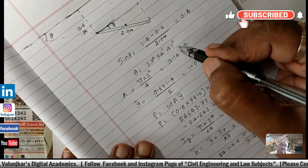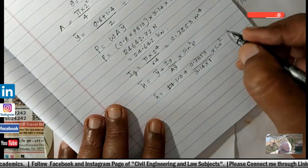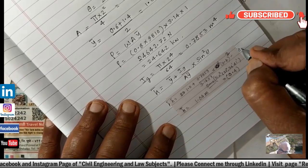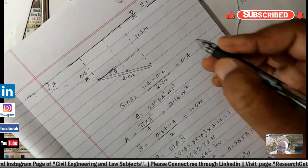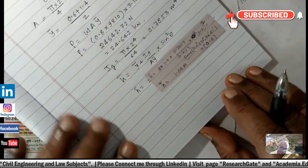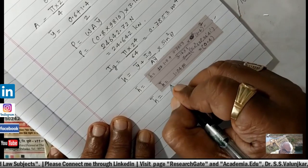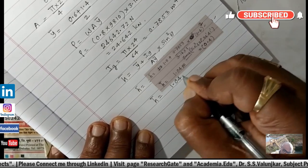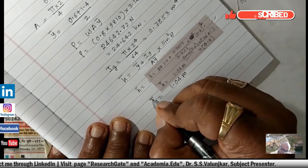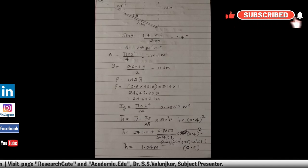The angle here is 23 degree 34 minute and 41 seconds, so sine square theta is 0.4 and we'll take it as 0.4. Then H bar is equal to 1.04 meter. Remember one thing, that H bar, the depth of center of pressure, always lies below the center of gravity.